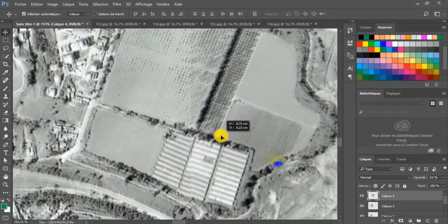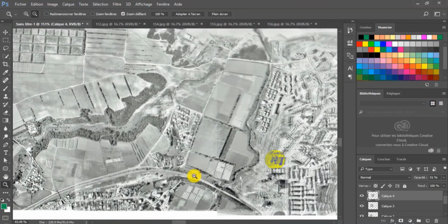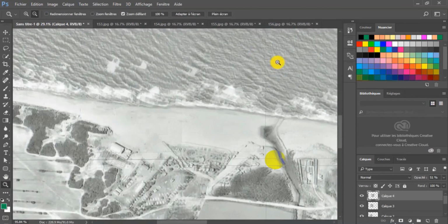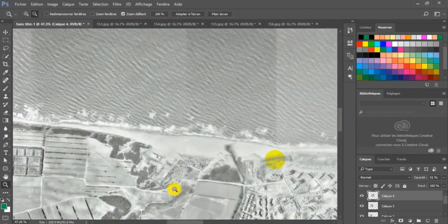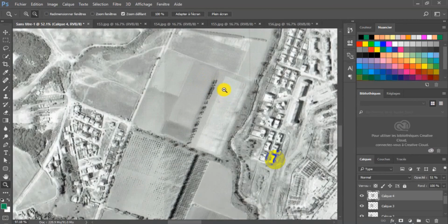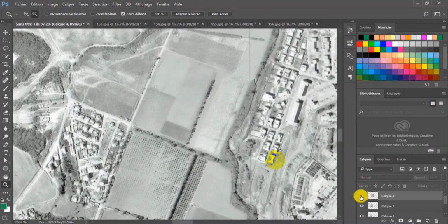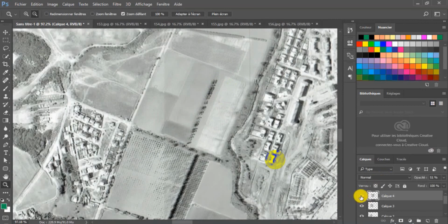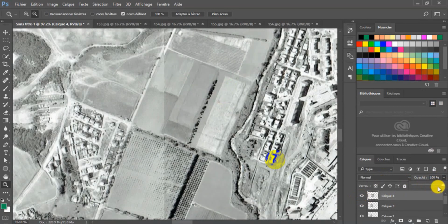See how difficult it is to assemble. That's why we require fiducial marks, coordinates, fiducial marks on the photograph, known points, positions. Everything is required. It's not easy to locate every detail and match between two photographs. And we also require at least 60% overlap to get the parallax errors.